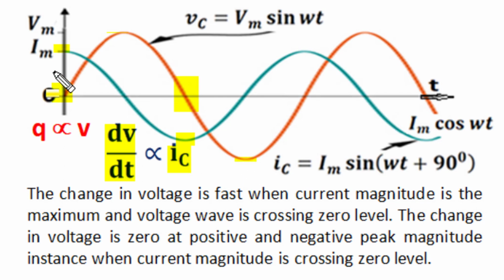negative peak, the rate of change of voltage with time becomes 0, as at those instants the charging or discharging current becomes 0. So when charging current is maximum, voltage is changing at maximum rate and charging increases voltage, and as charging current decreases, rate of change of voltage decreases, and when charging current becomes 0, the increase of voltage ceases, and when charging becomes discharging, the voltage in place of increasing starts decreasing.